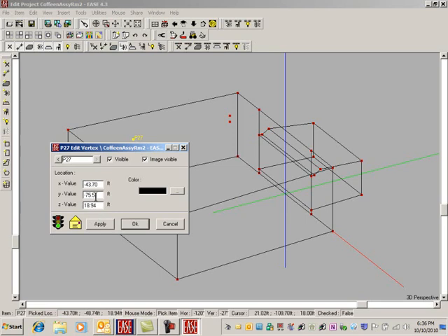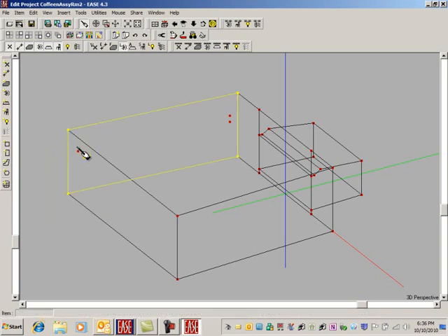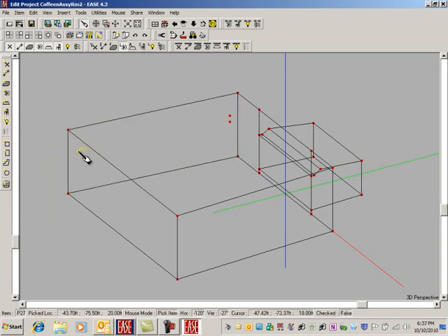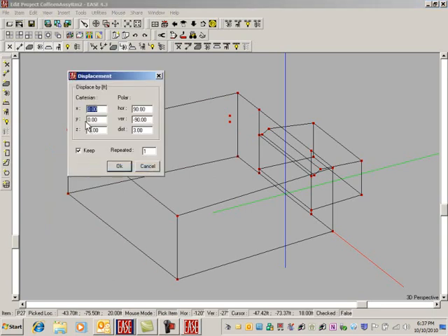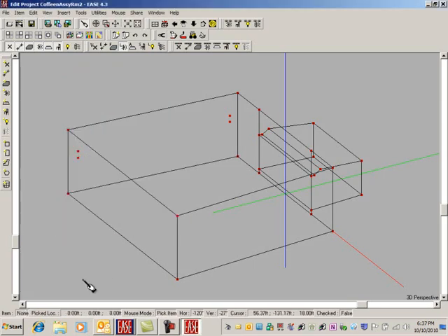I'm going to do an F6 again and save it. When I do that, I can close the edit face window if I like. Looks like I didn't get it closed to start with, so I'm just going to say cancel that window. And I can always close this window now. And I'm going to save my project. It's already saved, but I like to double click twice there on Save Project, and it's OK. So now I've saved this project.